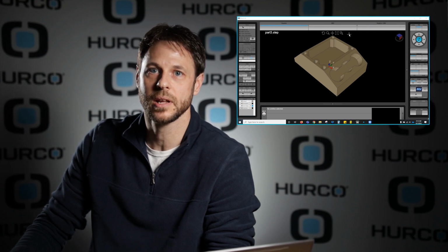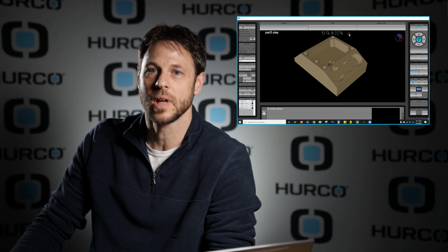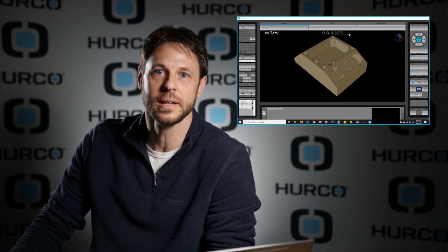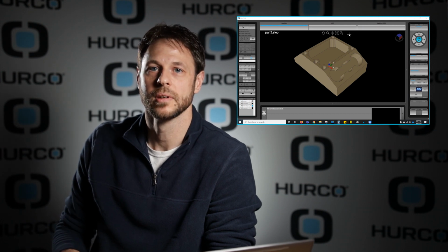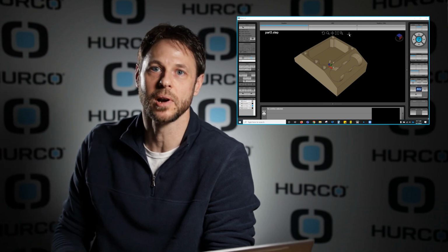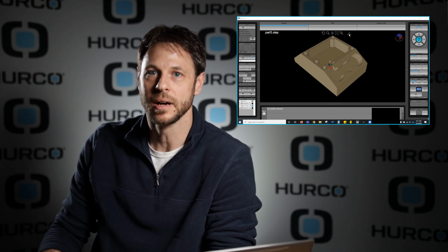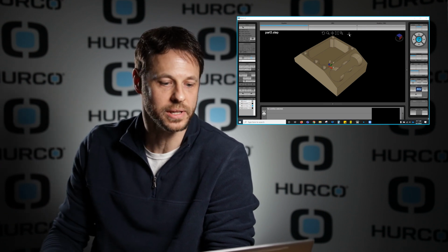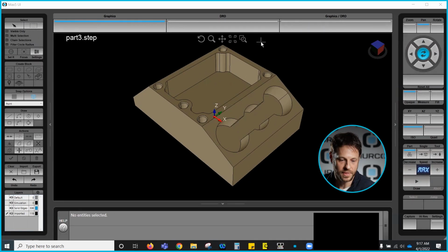In previous videos, we've mentioned that this is one of the most important steps when working with the solid model or DXF or 3D DXF options. This is because all these data blocks are going to be created based on this part zero. So you want to make sure you have that where you want it on the part and very accurately on a feature, either endpoint, midpoint, or that kind of thing. So let's show you a couple things with that.